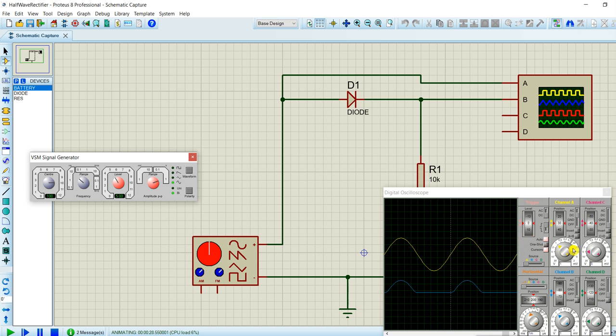I think peak to peak voltage is 5 volt. Let us count it here. One box is 2 volt, so it is 5 volt. So peak to peak voltage is 5 volt. It means there is 2.5 volt going negative. So if we apply 2.5 volt or more in the input on the positive side, forward bias, then what will we get? By the principle of superposition, this side will always be at positive voltage.